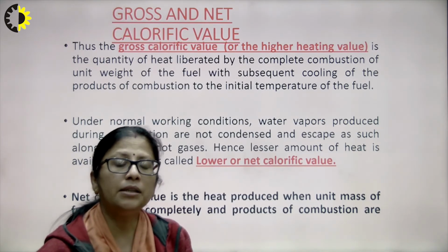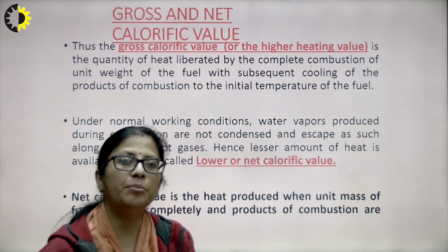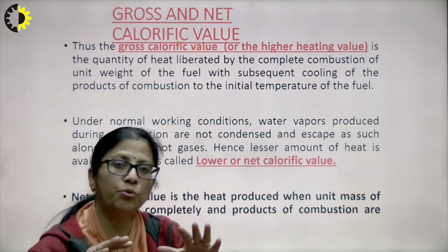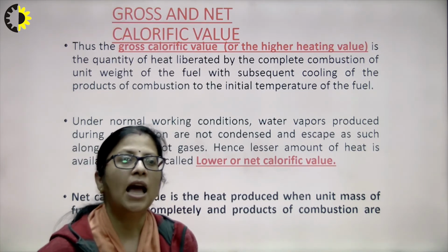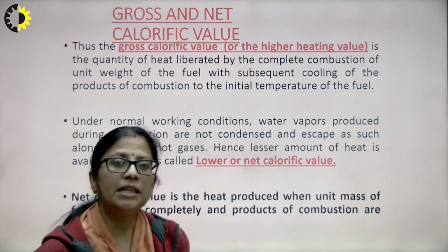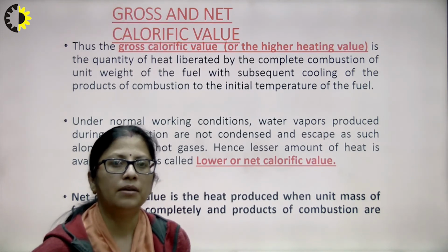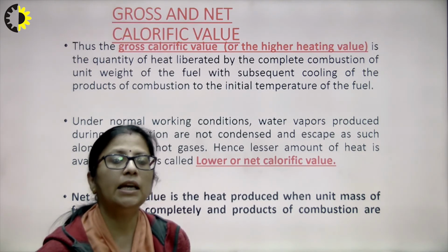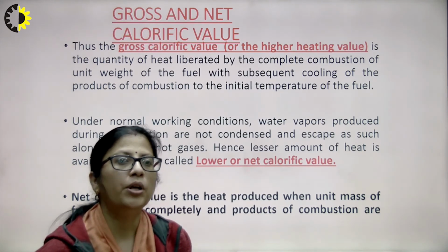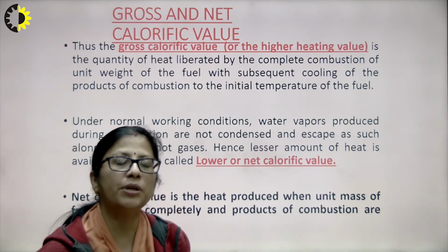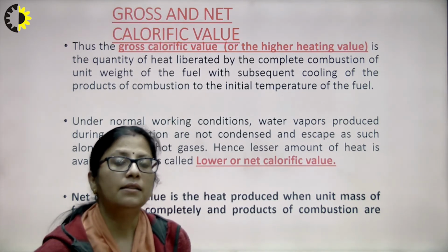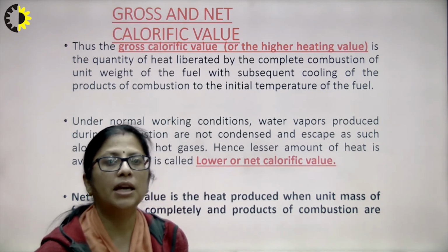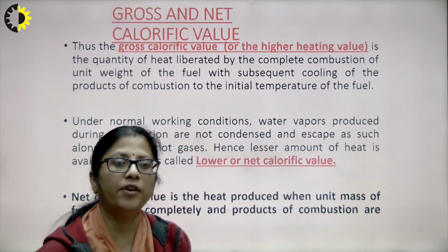So, when I burn the fuel, the products after burning are going to cool down in the bomb calorimeter, and the latent heat of combustion of steam, the water, is also going to get included in the calorific value. So, the products of combustion are going to get cooled down, and their latent heat is also going to get counted in the calorific value.